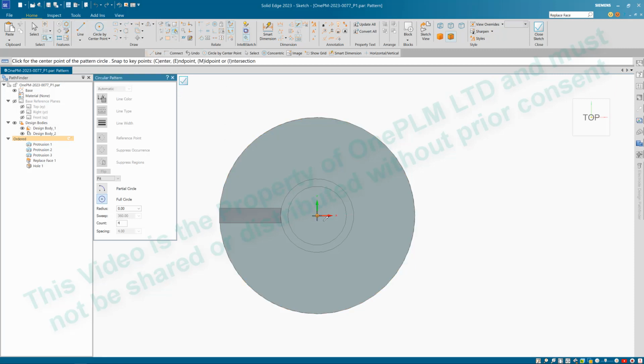So for the pattern, we're going to select the origin, and then we're going to drag out to a key point. So I'm going to drag out to that key point, and then in this little box I'm going to select 3 and tab. And we're then going to see what that will look like.